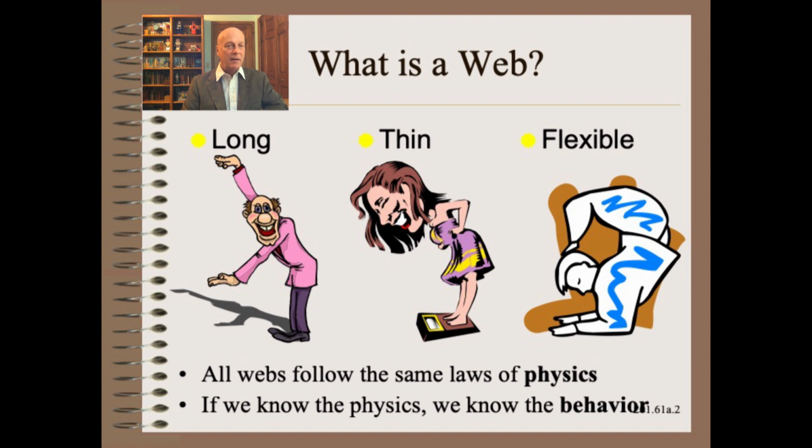If you see a wrinkle, for example, you diagnose it using the same set of tools, no matter whether it is on paper or film. If you see a web break, you diagnose it using the same set of tools, no matter whether it is on foil or paper. If you see a wound roll defect, such as telescoping, you diagnose it the same way, no matter what the chemistry. This is convenient. One set of rules for all materials.